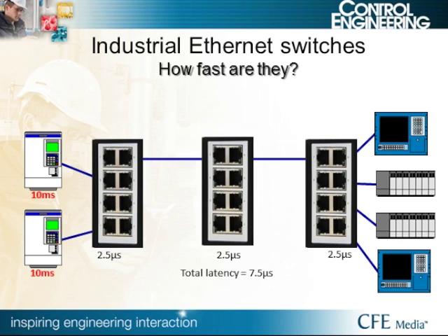For network switches to add 1 millisecond of latency to the communications path between the drive and the PLC, there would have to be 400 switches between them if you add up that 2.5 microseconds of latency. Today's modern switches are rarely the bottleneck to a network. In most cases, the devices on the control network are the reason for the slowdown, not the switches themselves. Large enterprise switches now have latencies measured in the 200 to 400 nanosecond range.